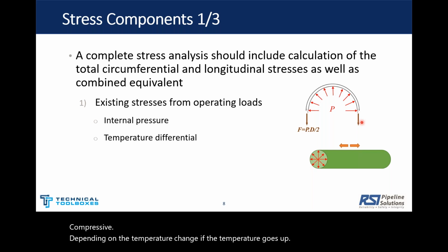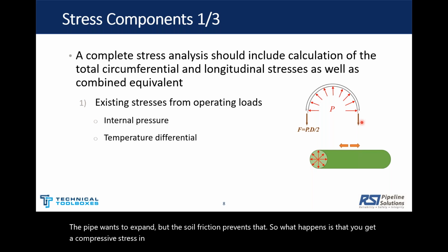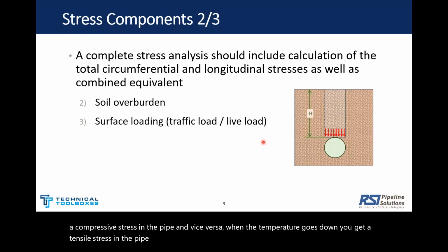If the temperature is up, the pipe wants to expand, but the soil friction prevents that. So what happens is that you get a compressive stress in the pipe, and vice versa. When the temperature goes down, you get a tensile stress in the pipe. All right. So those are the operating stresses.